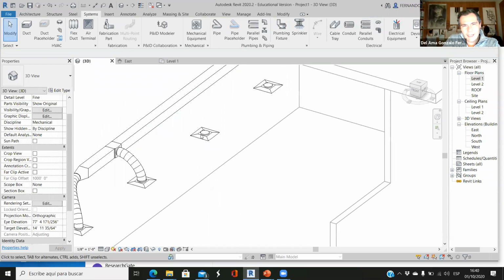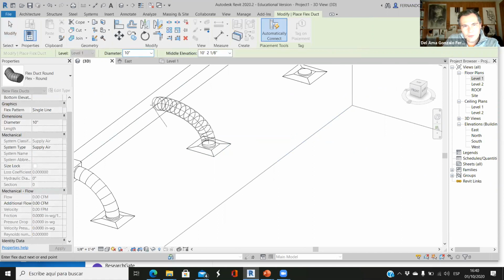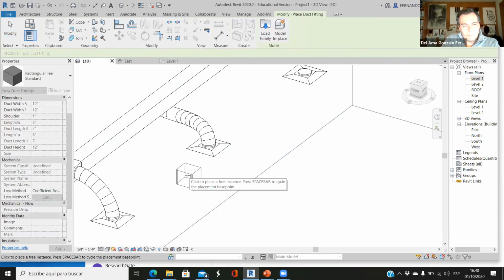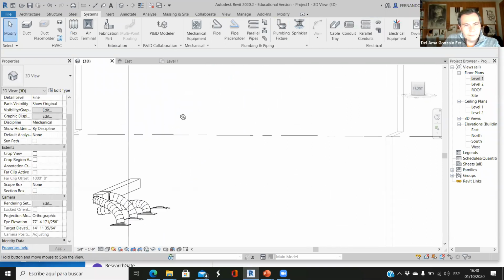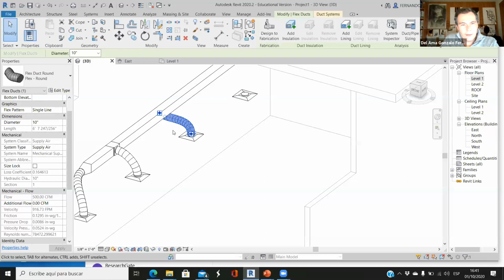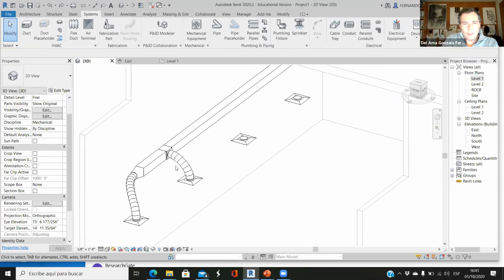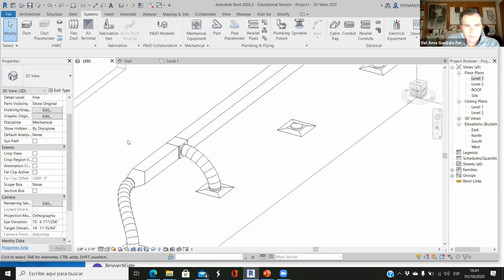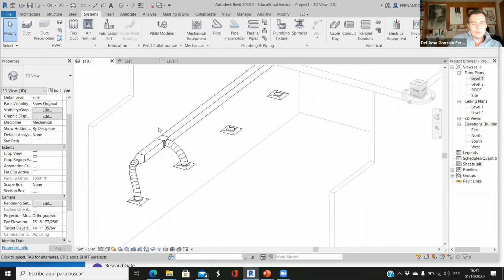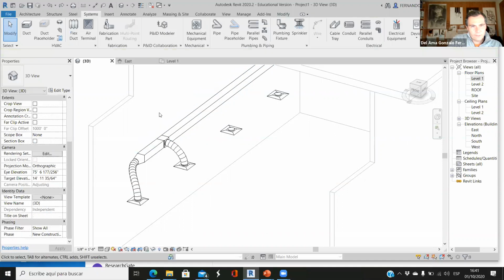So if this doesn't work, if I click here, draw flexible duct, and then I try to do this, well, I don't know why, but this doesn't work directly. So I think I have to place more T's here, and then we can do this many times. But first, I want to check whether what we are doing is right or wrong. And apparently it is wrong. Okay.